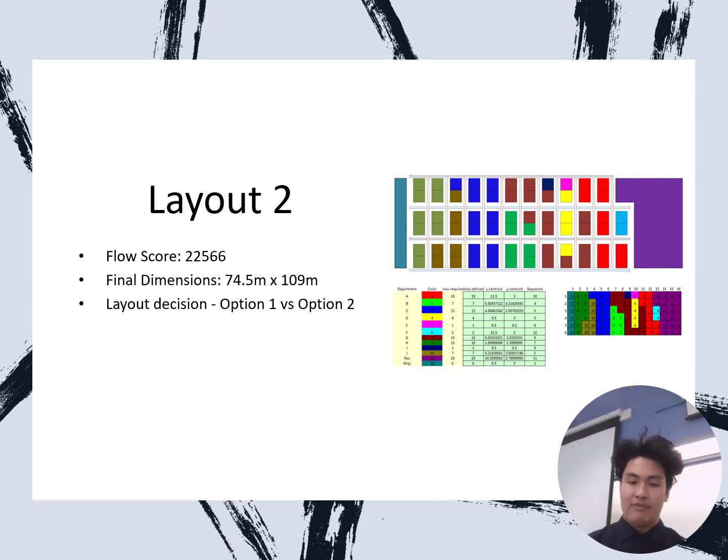So why, if the flow is so much better here, are we going with layout 1? Well, it's because layout 1 and its U shape has a lot of benefits that are not measurable, like how if you have both on the one side there, capital costs for storage equipment can be shared instead of having to buy 2 separate storage equipments.